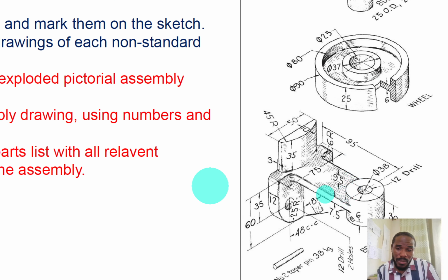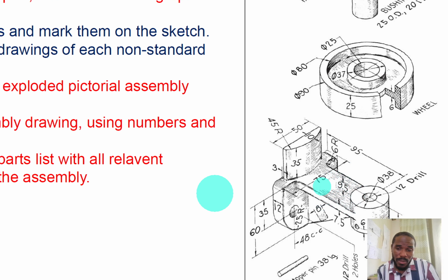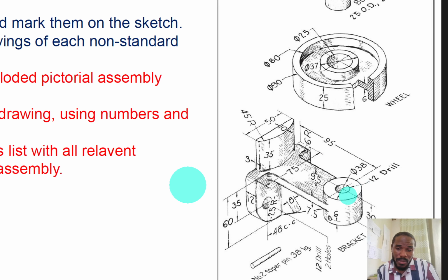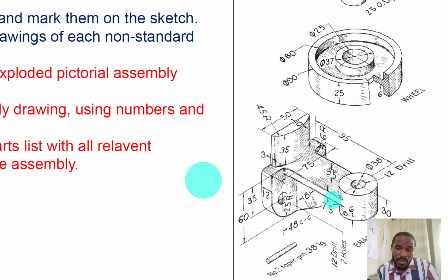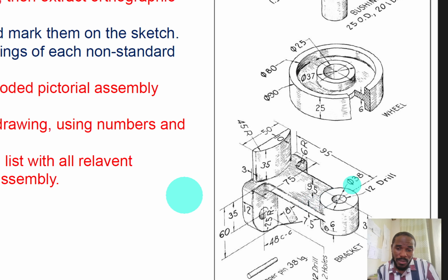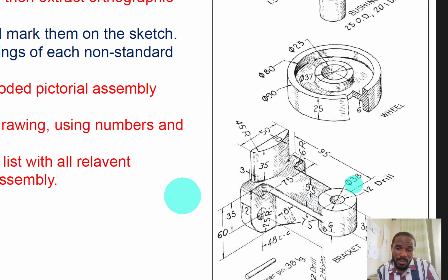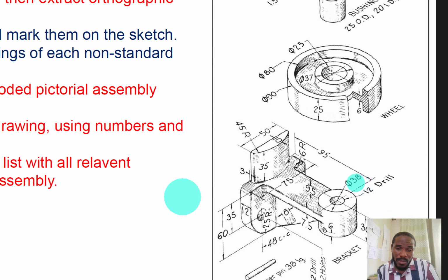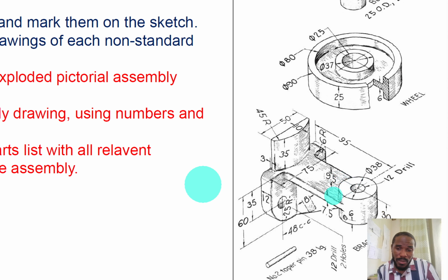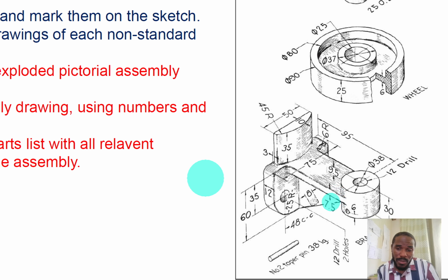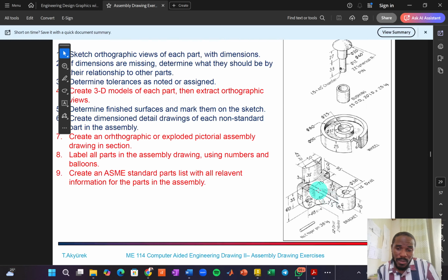And the width of this is the same as the diameter, because look at how it flushes into that. It's the same as the diameter of this cylinder. So I take the width to be 38. So I'm looking for a simple rectangle 95 millimeters by 38. And then when I am extruding, I'm extruding downwards by 7.5. Keep those dimensions in mind.